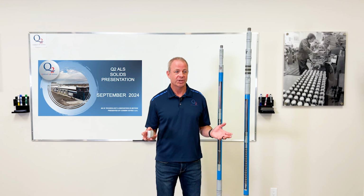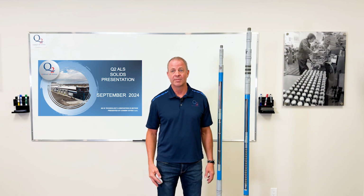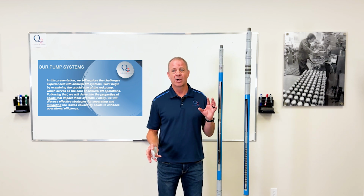A lot of production engineers in the oil field right now are battling solids from our formation in our downhole rod pumps, so we'll talk quite a bit about that today. There's a crucial role in rod pumps, and the heart of the system are the valves and the plunger.